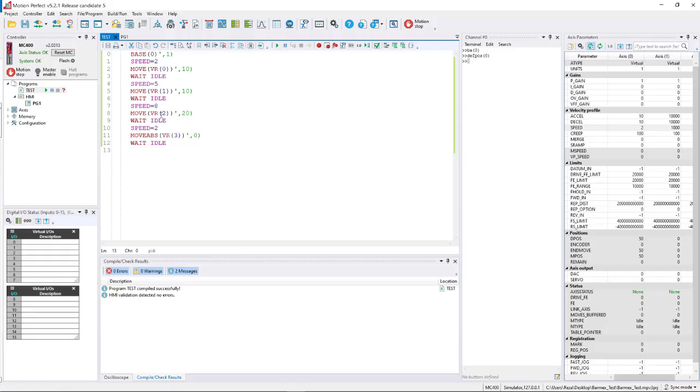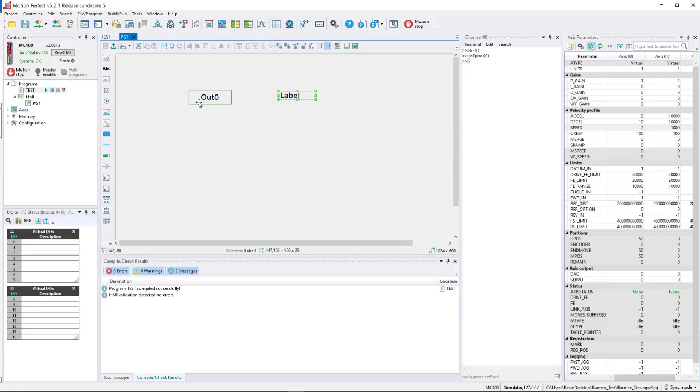So instead of having a fixed number, now I set up a variable for that. This variable can be accessible over the HMI for us. So I can go to the HMI page over here, and instead of a display, I can add more options from the editable text option.